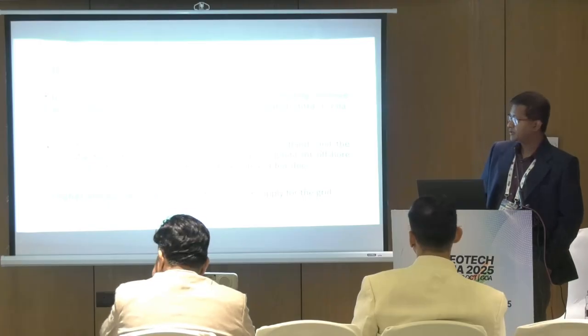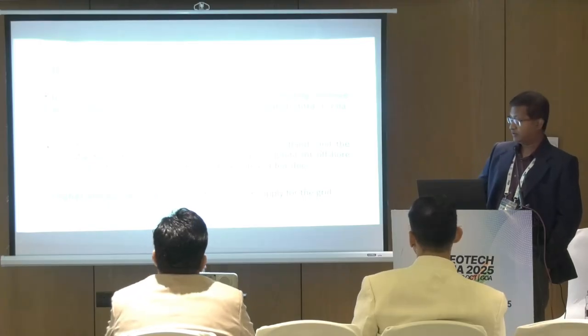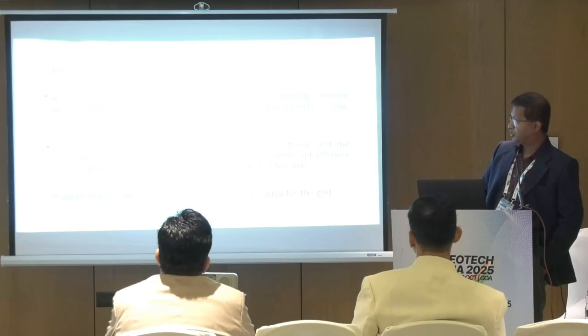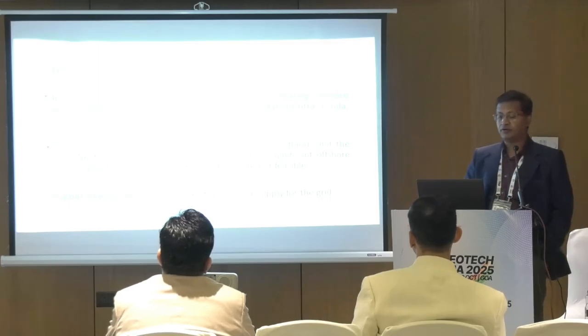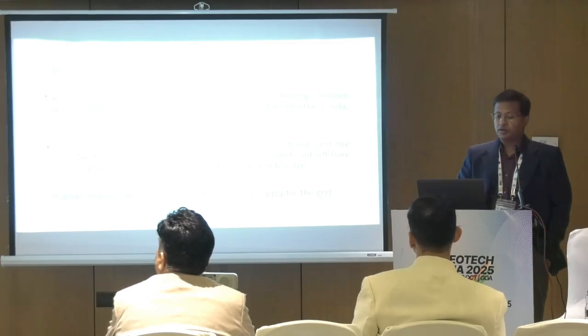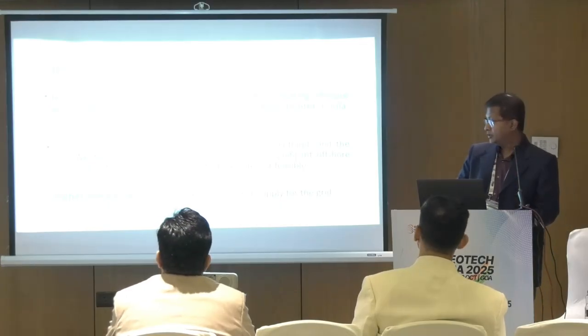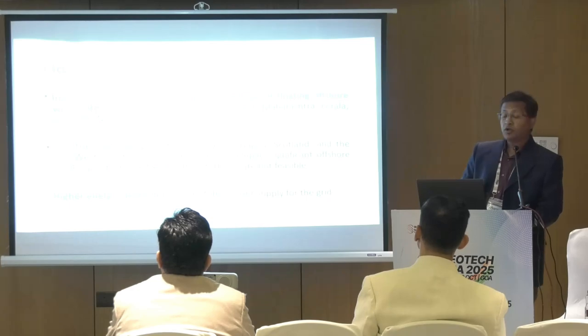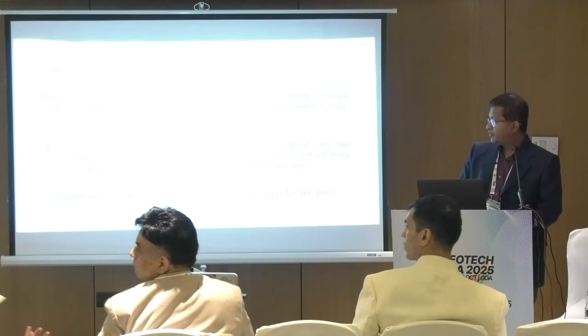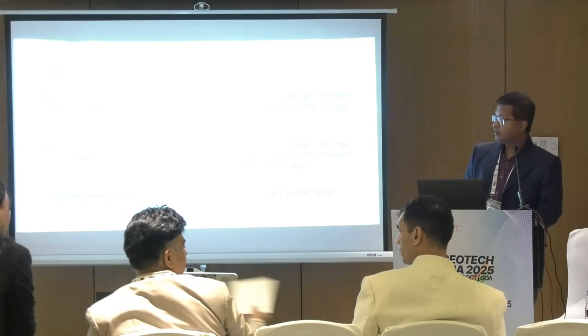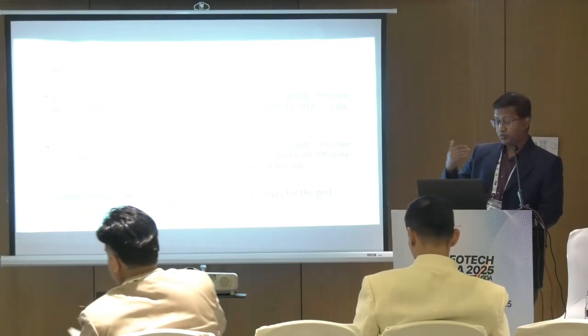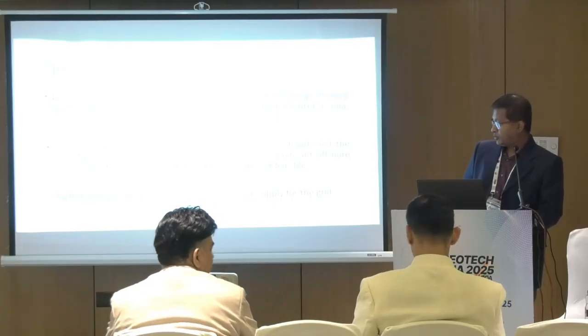Based on the feasibility study, it has been seen that there is a potential of 112 gigawatt of bottom-fixed and 83 gigawatt of floating offshore wind, mostly in Gujarat, Maharashtra, Kerala, and Tamil Nadu. And for countries with deep continental shelves, I'll talk about what a continental shelf is and why it is important. Mostly in Japan, Scotland, and the US west coast, you may find the continental shelf is very narrow, and the deep water comes very early from the coastline.